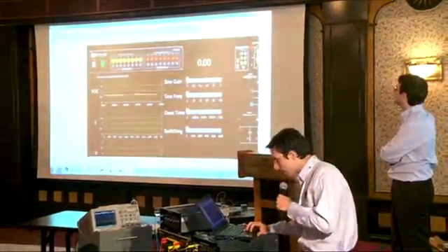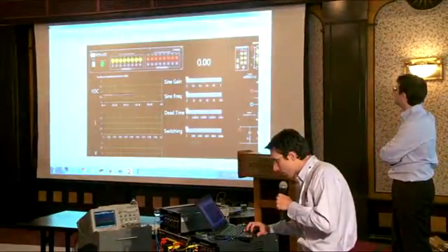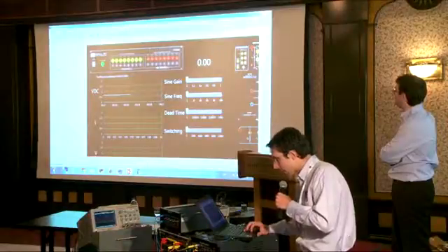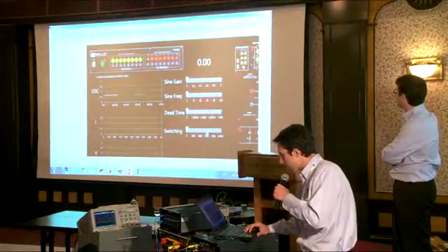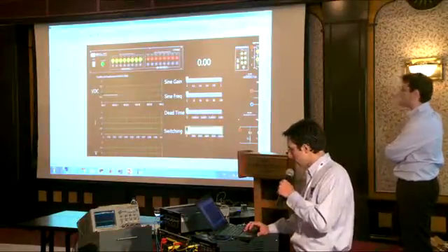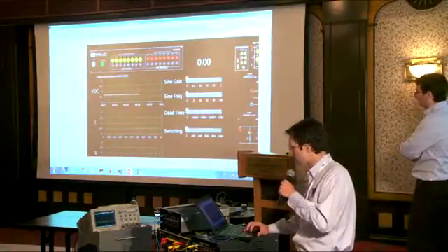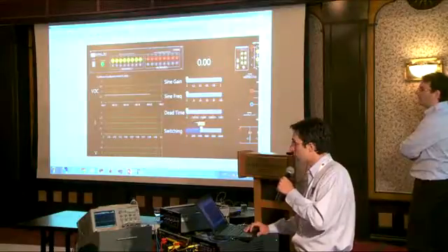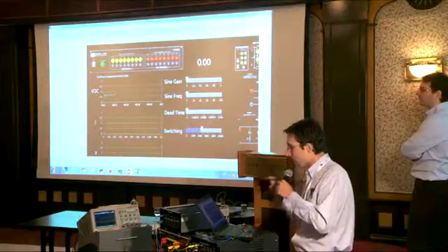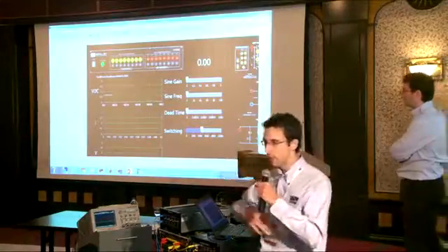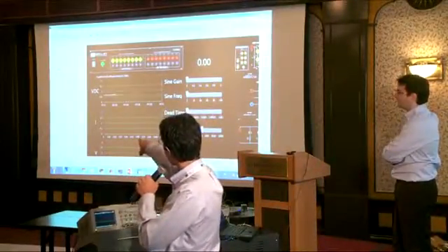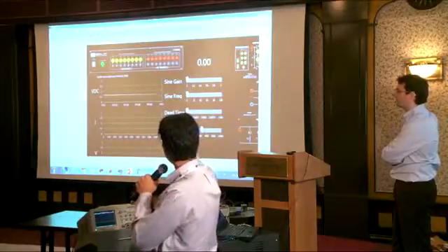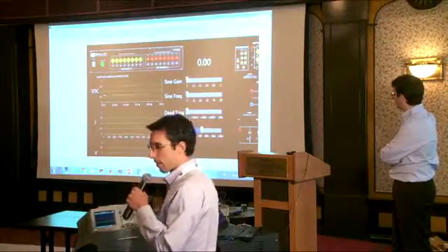I can say, okay, let's now go into the IO. We can go to the carrier blocks and say, okay, let's take the frequency number 0 and drag this to the switching frequency that we have here. So now instead of changing a parameter on the model, I'm actually changing the switching frequency directly inside the FPGA. So I don't even go to the Simulink model. I just map an FPGA parameter that is actually running on the IOs to the UI. So right on the fly.